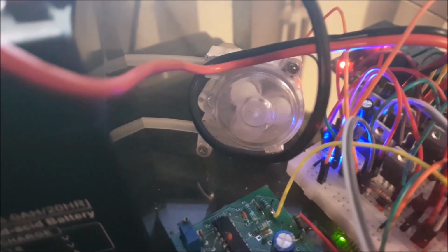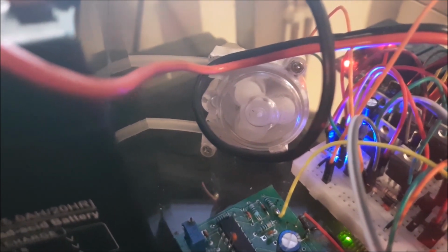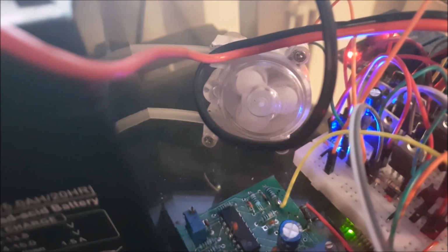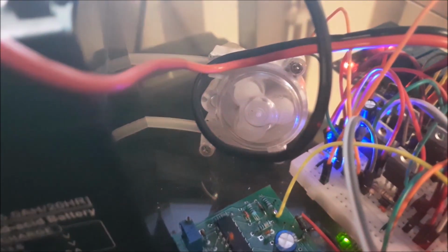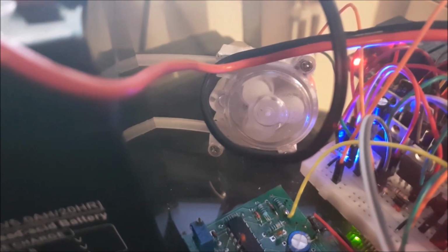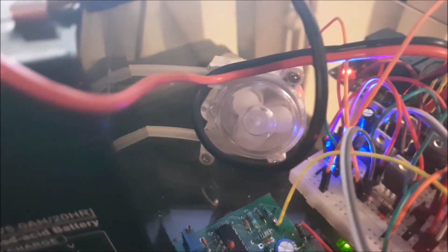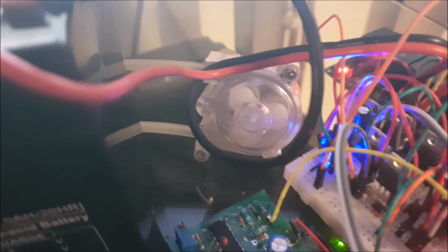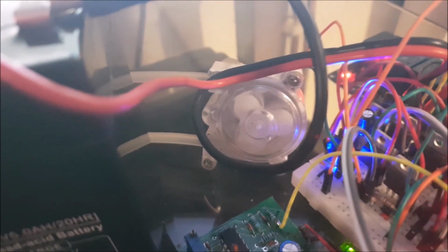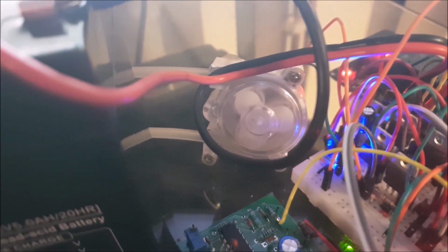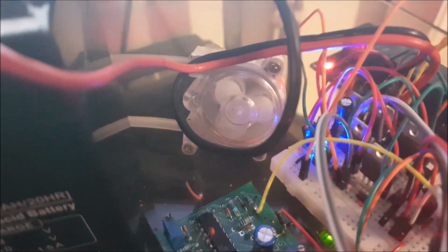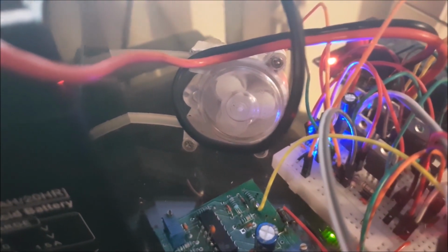So my doses run merely on the basis of being calibrated for 1 milliliter per second. This can be achieved through the PWM and using a potentiometer on the motor itself, and even if you must, you can adjust the interval in the software for extra calibration, but really the potentiometer on its own should be enough to get it to do 1 revolution per second, or adjusting the PWM. Certainly both combined would be enough. You shouldn't need to go into the software and do any more.